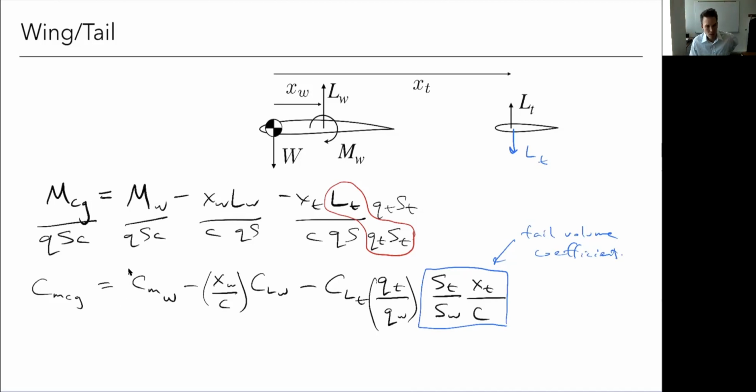Okay, so let's see. I guess we could go through the same analysis. It's going to be the same as we saw last time. So the aerodynamic center thing, that didn't change at all. So that stability thing, that was universal. When we did that stability analysis, we had an aerodynamic center. That was for the entire aircraft. So it doesn't matter how many tails or lifting surfaces there are, where they are, fuselage or whatever. All of that was wrapped into one.